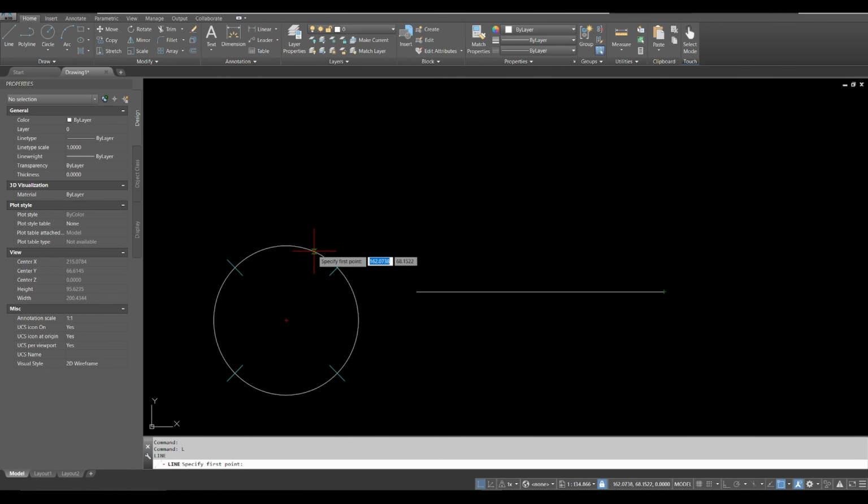Likewise for the circle. I'll have nearest. I'll also get a center snap. I'll get a quadrant snap. I'll get midpoints and endpoints on each of these lines. And you can see that it's very easy to make a mistake, right? If I were working very quickly and go, oh, I want the endpoint, and I click here, assuming that the endpoint snap is going to activate. Well, unfortunately it didn't, and now my line is in the wrong place, starting from the wrong place, right?